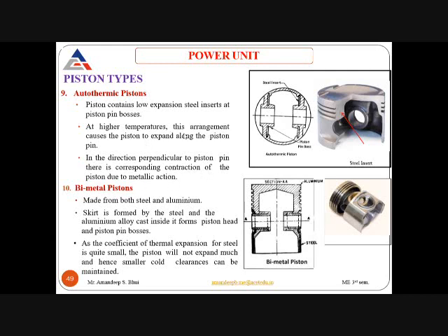At higher temperature, this arrangement causes the piston to expand along the piston pin. So along the piston pin the piston will expand, but perpendicular to the piston pin the piston will not expand. These autothermic pistons are provided with these low expansion steel inserts.